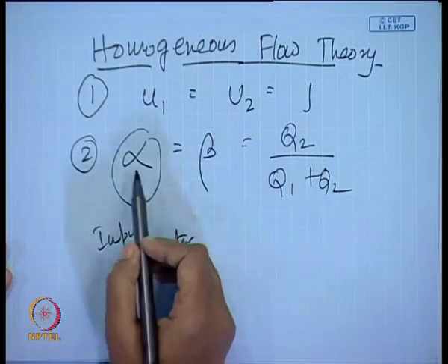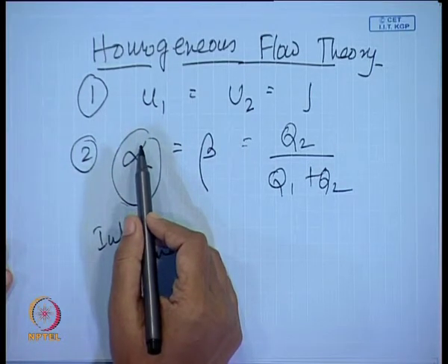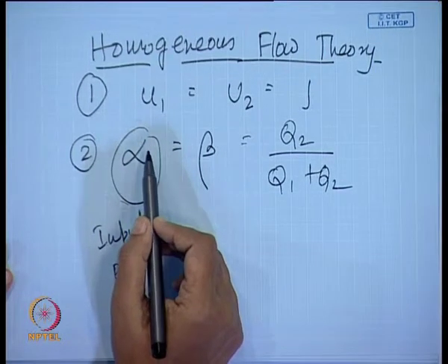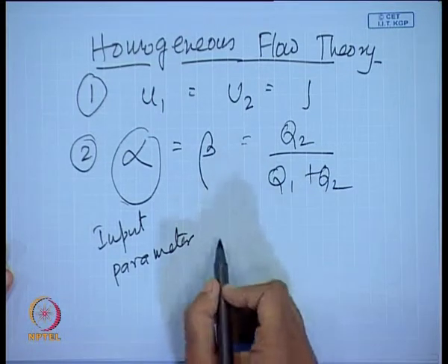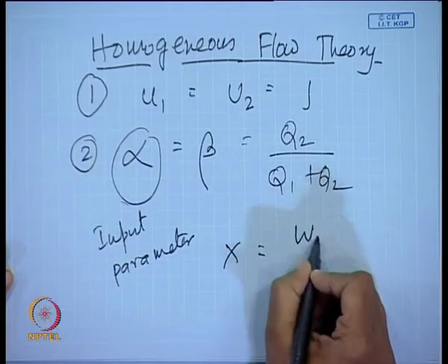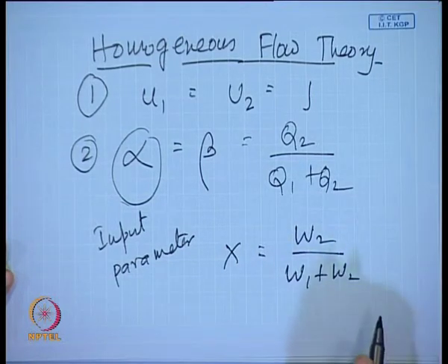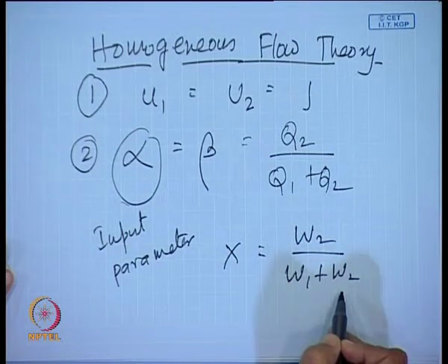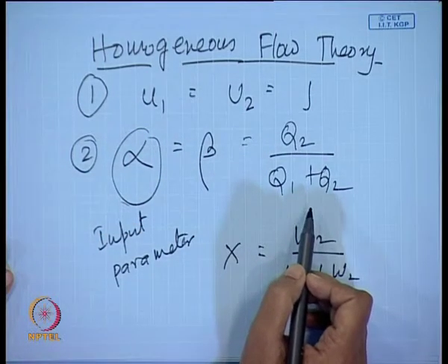This has given us that the inlet void fraction and the in situ void fraction have become equal, or in other words the void fraction or the in situ composition is nothing but a measurable parameter. So, just for recapitulation, suppose there is evaporation, condensation or boiling, then in that case we can obtain the quality from the inlet mass fraction, and the void fraction from the inlet volumetric flow rate.